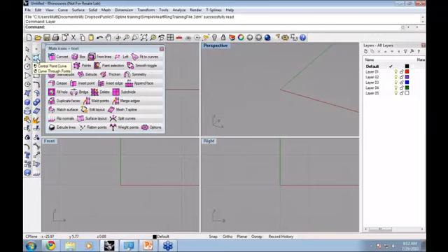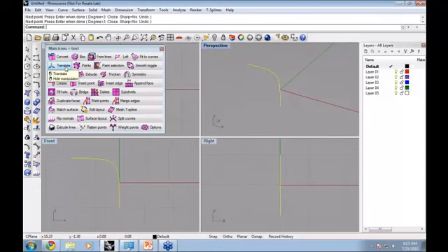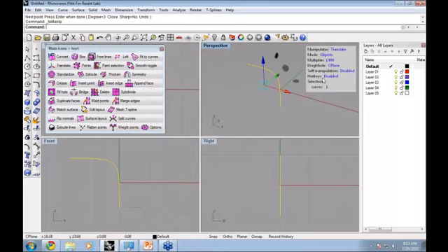Let's lay out a Rhino curve to see how this command can work. I'm just going to add a few control points here. Then I'll grab this curve and open up my T-Splines manipulator. When I open this up, I have my heads-up display, which tells me a lot of information about how I can be using T-Splines. This tells me I have my translate manipulator up, and if I drag on this curve with the arrows, you can see it moves the curve around in the scene. These disks will keep it in the plane.